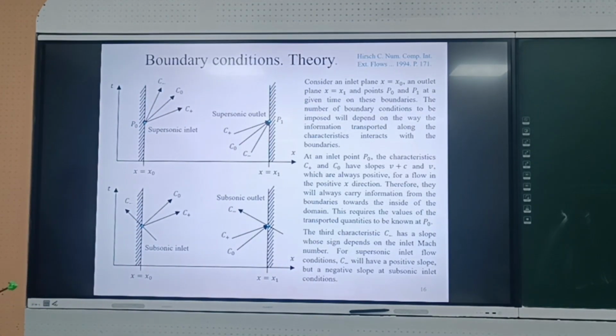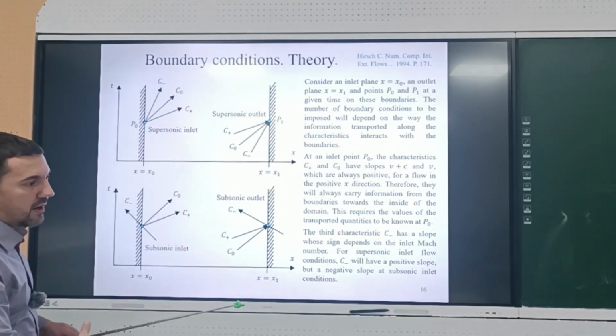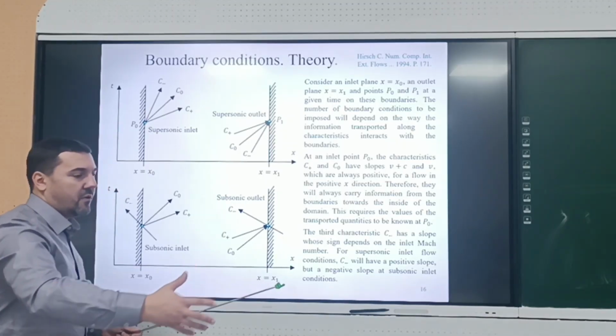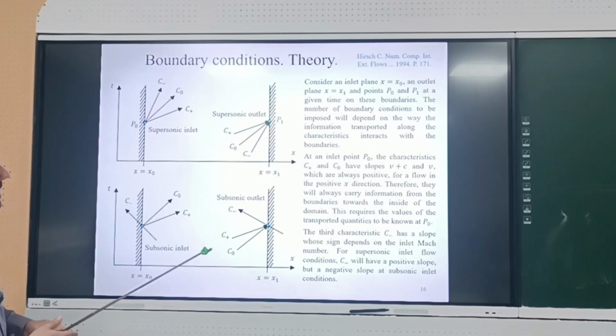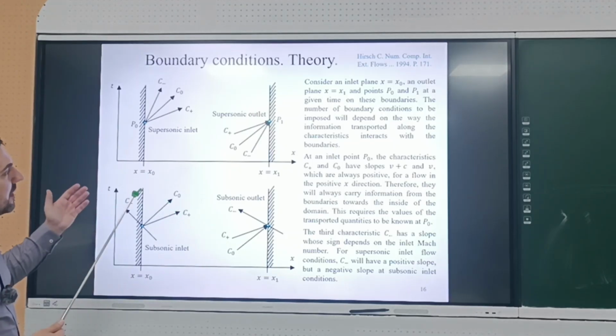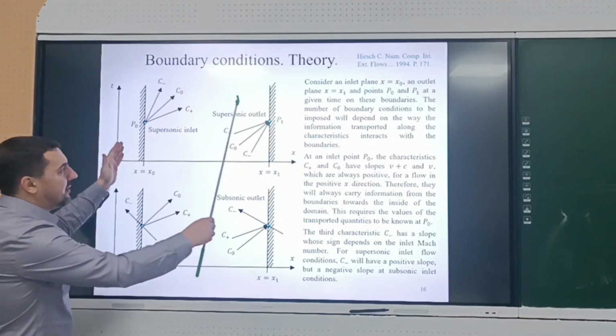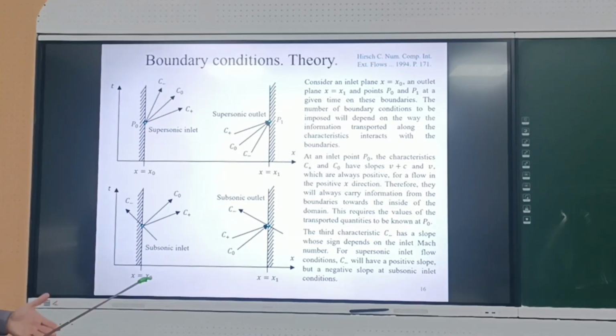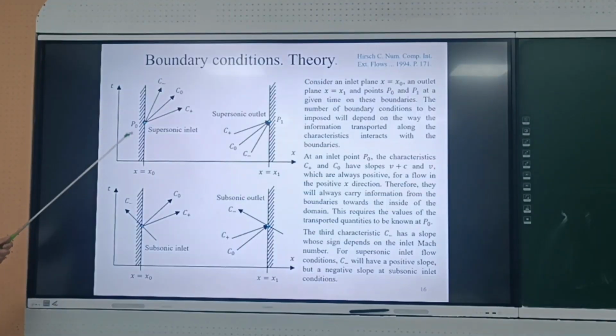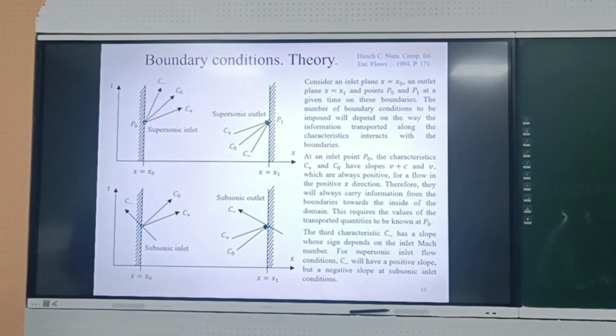If we were able to simulate the whole shock tube or the whole duct of our engine, considering all walls, there would be no problem. But usually we are not able to do that. That is why we need to compute only part of our device, and because of that we should somehow define the inflow conditions and outflow conditions.